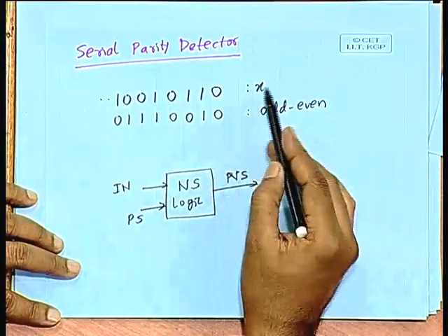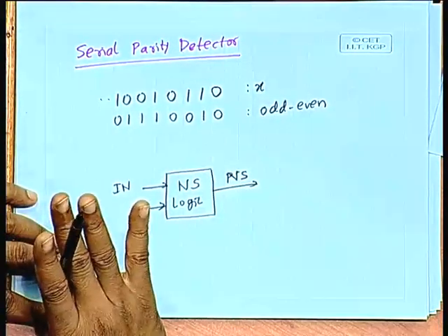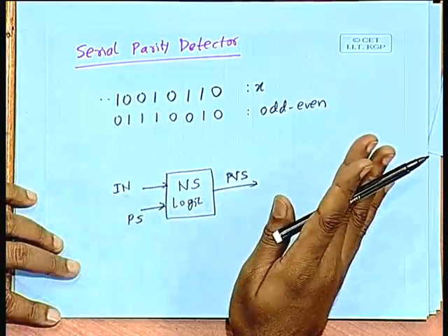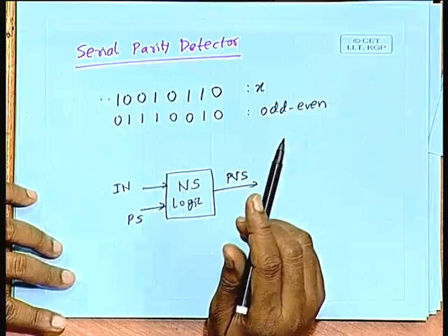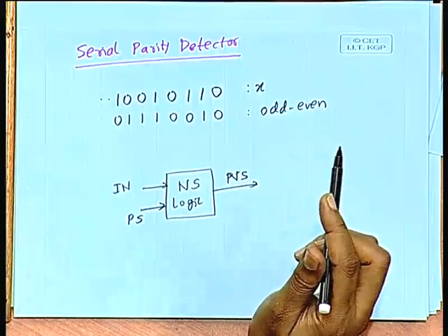For the output you do not need x, this is what I mean. So, this you can categorize as a Moore machine, this is not really a Mealy machine. But the way we wrote the code, it looked like a Mealy machine. We tried to mix them up, but actually the way it is working, it is independent of the input. Whatever state you are in, from the state you can directly derive what should be the output at the current point. Okay. Fine.